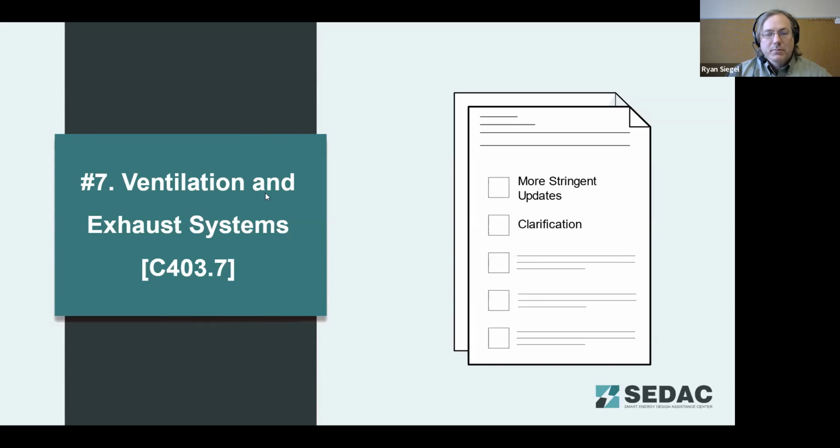Is it that heat pumps are very efficient, so an economizer is of minimal benefit? VRF can recover energy internally, so free heating and cooling is already accomplished by the system. Maintenance of multiple smaller economizers is too expensive, or VRF systems don't draw enough outdoor air to efficiently economize.